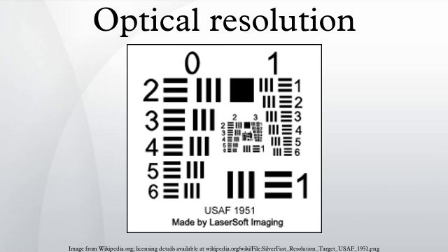Smaller pixels result in wider MTF curves and thus better detection of higher frequency energy. This is analogous to taking the Fourier transform of a signal sampling function. As in that case, the dominant factor is the sampling period, which is analogous to the size of the picture element. Other factors include pixel noise, pixel crosstalk, substrate penetration, and fill factor.